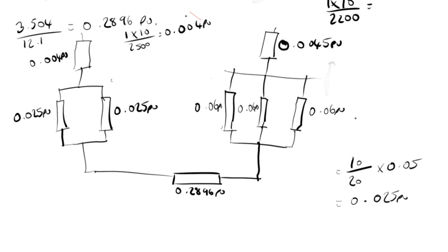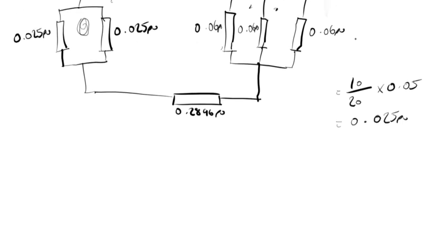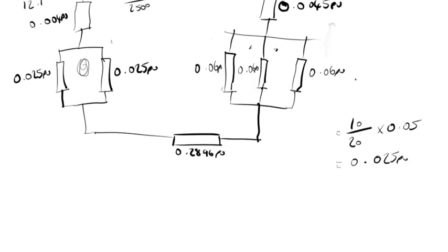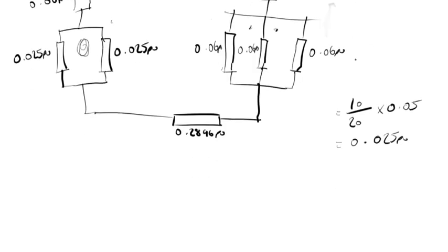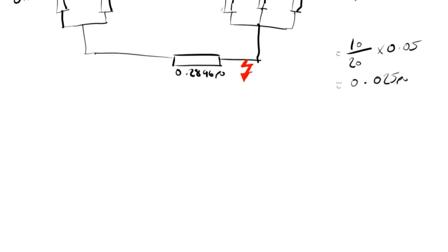So if we imagine that a fault turns up at this point in the network, so it's a fault to earth, what we have to do is display all these values. So that's your substation A, maybe 2 transformers just here. This one's also 0.025 pu as calculated before.